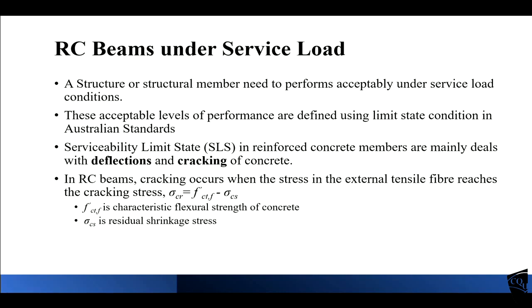The shrinkage will happen over the life of the beam, generally up to at least 30 years. As time goes, that will increase. So the shrinkage stresses need to be subtracted because concrete has significant shrinkage loss, so we just need to reduce for that.